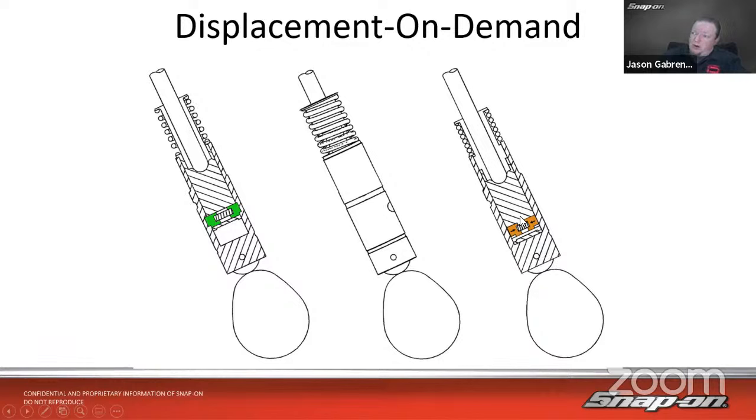When we want to turn off some cylinders, once again, it's an oil-controlled solenoid valve. Oil pressure goes in, pushes against the springs, pops those pins out. So now the outside can open independently of the inside. So the inside basically stays in place, and the outside slides over that inside part, allowing it to follow the camshaft but not push the push rod. So in effect, those valves are all closed and they're not able to open at that point. So it can turn off those particular cylinders.